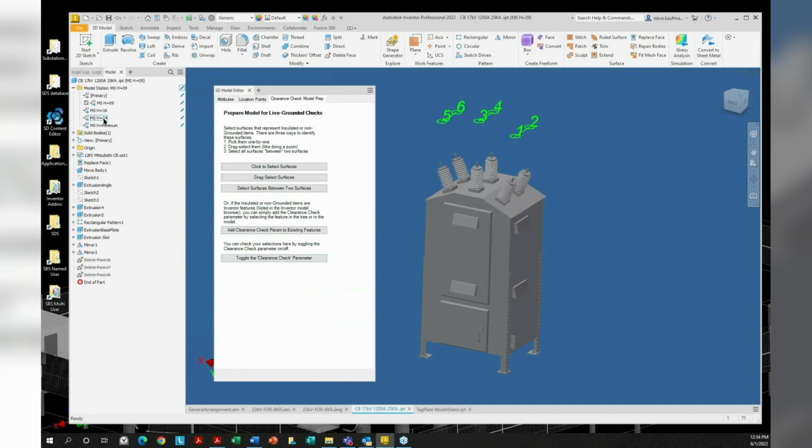So you may want to make your model states for the changes you want before you do the suppression. You want to do the suppressions in factory scope, and probably after you make all of the types you want. Otherwise, you have to go into each new one that you make and edit it.